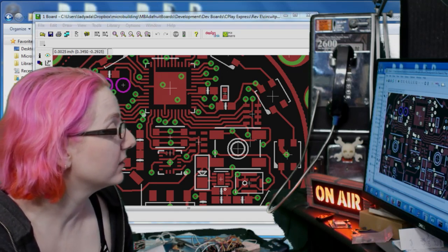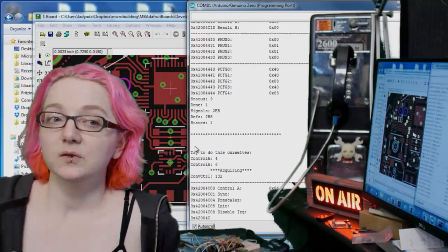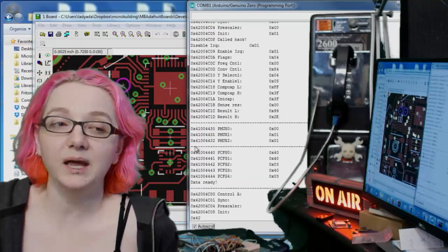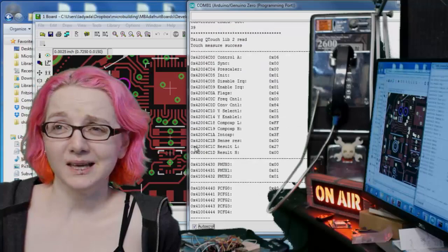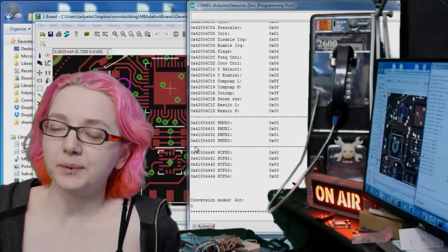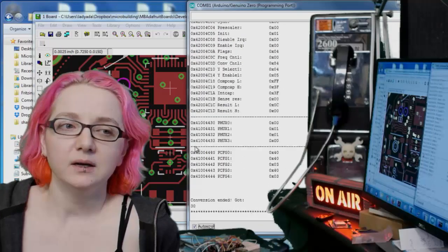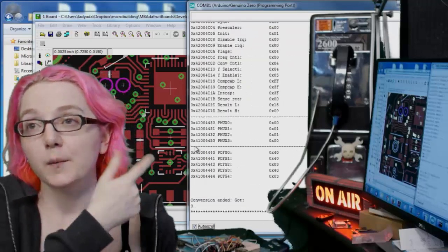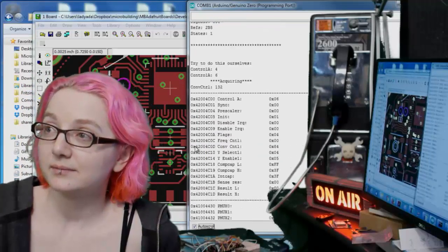So all of that work really was just to get rid of these 2 parts. But it'll also make it possible for us to use the Circuit Playground with CircuitPython without needing a lot of overhead code. This library linking it in is a pain. It'll be faster because I can read 1 sensor at a time, and also I can use it with weird linked stuff like PXT, where they don't use a compiler, they link code in. So linking in an external library is complicated. So all good news, and of course Arduino as well. You can't link external libraries with Arduino, but with my code, because I'm twiddling the bits directly, it's going to work just fine.